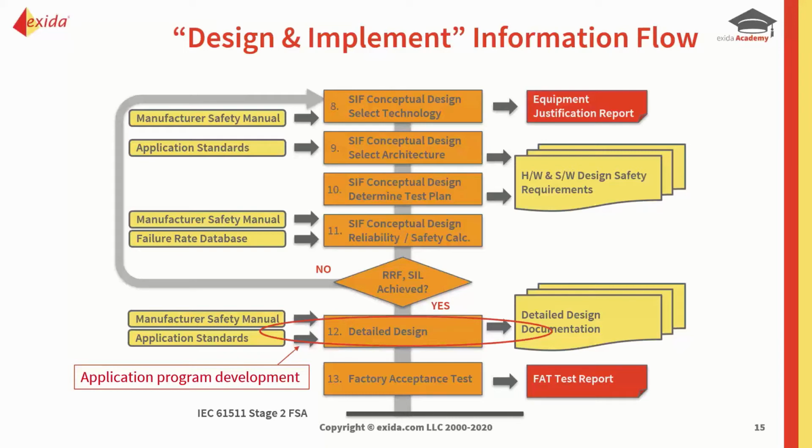That's known as white box testing because you can see what's going on. Black box testing is where you have inputs you stimulate and then you look for the equivalent outputs. You don't see what goes on in the middle. And that's typically what happens during a factory acceptance test. So let's look at this then.